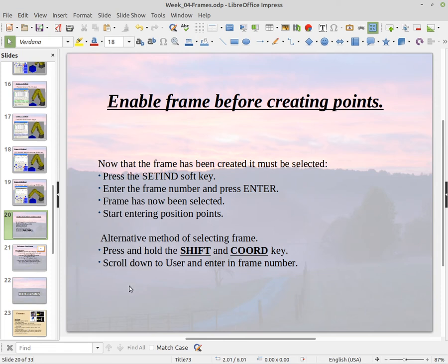Now, one thing about jog frames is they are only for jogging the robot. As I mentioned earlier, every point in a program, unless it's stored as joints, is stored based on the user frame and the tool frame. But the jog frame is only for jogging the robot.